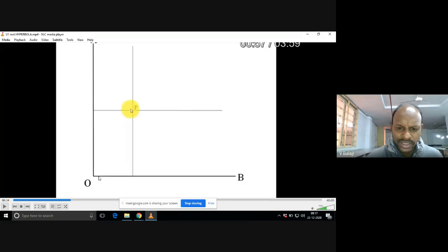Automatically, the other mini drafter scale shows 90 degrees, right? You can easily draw OA. That is the advantage of the mini drafter. Without the mini drafter, please don't draw anything on the drawing sheet. It's a good habit to use the mini drafter all the time. Thereafter, as I said, these two straight lines are nothing but two asymptotes, 90 degrees to each other.